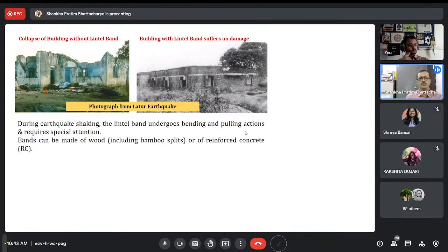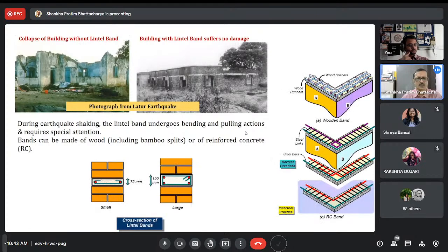So now you may say that it is going to cost you. Yeah, costs, but see what the section details are also. So below you see you may actually go with a 75 mm small RCC with 2 reinforcement bars. Enough.